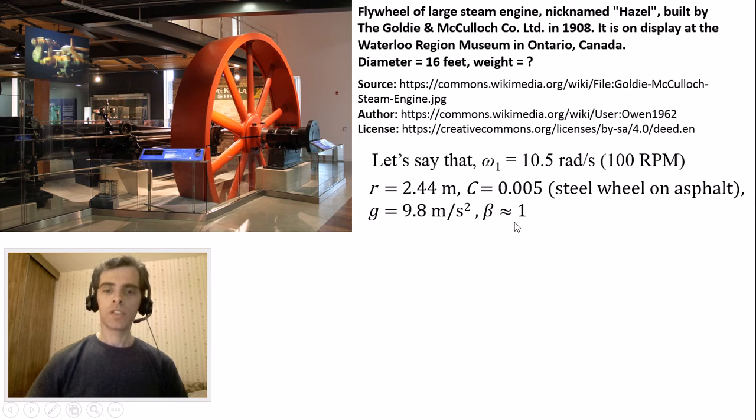You remember that initially we said that Ig, which is the rotational inertia of the wheel about the center of mass g, is equal to beta times m r squared. For a flywheel such as this, it's approximately a hoop shape since most of the mass is distributed around the outside perimeter, so we can say that beta is approximately equal to 1, although not quite, but close enough.